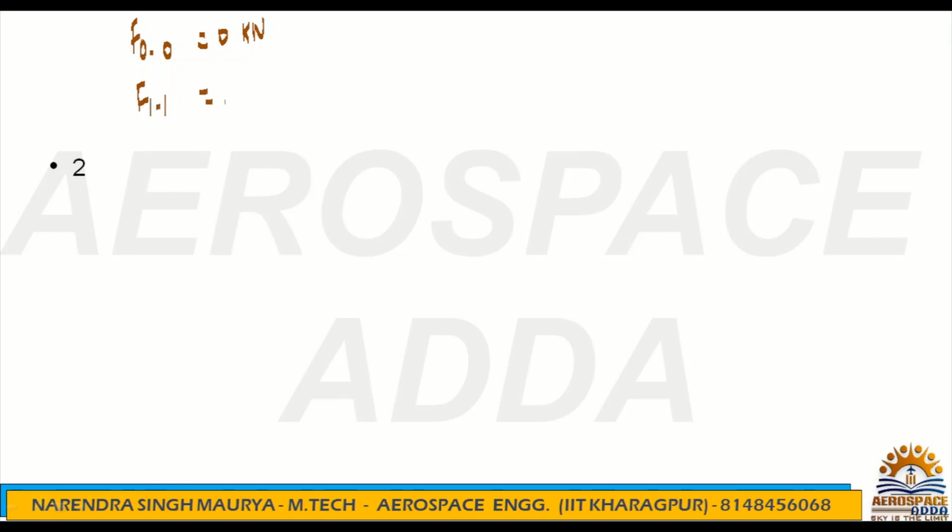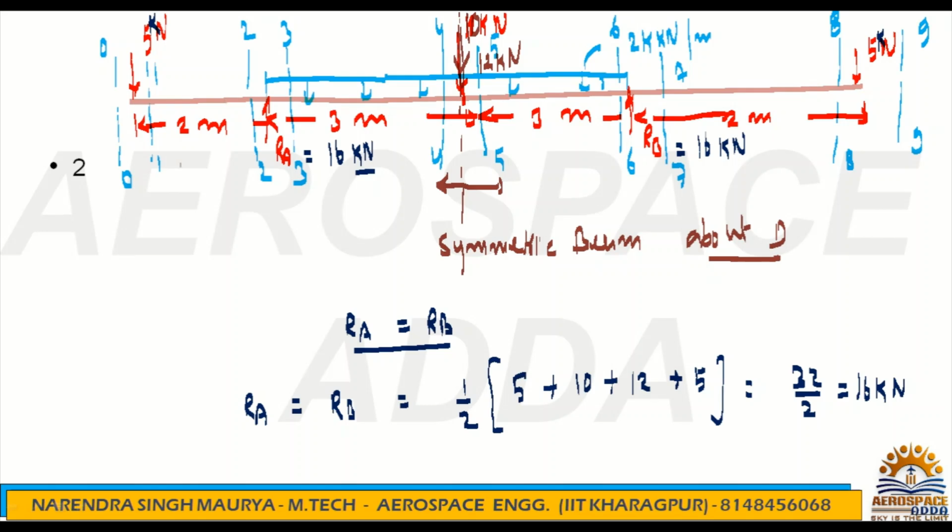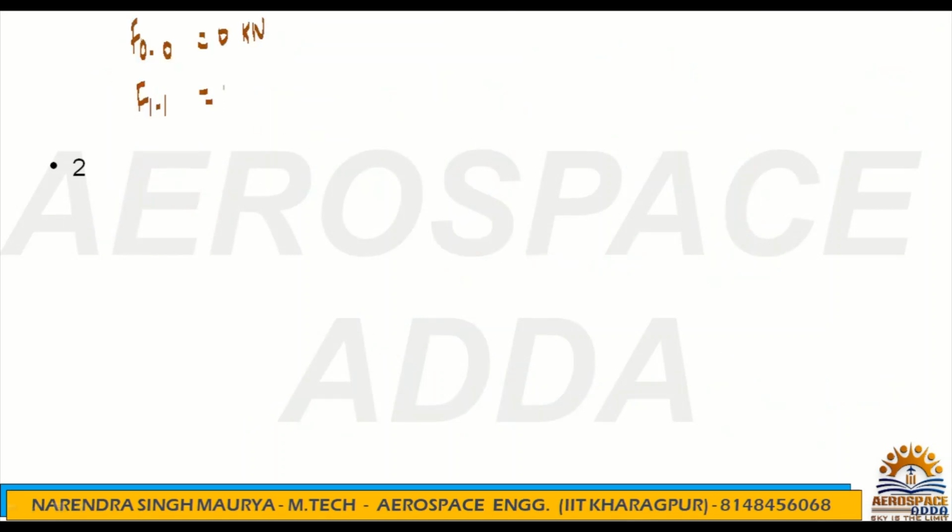It is just after the force, after the 5 kilonewton. For 1 1, you can say left or right. This is the right of the force, and this is the left of the force. In a few books you may get left of the 5 kilonewton. So the left side of the 5 kilonewton, 0 0, the value will be 0, because the force starts after the 0 0 line. And if you check 1 1, before the 1 1 line, one force is there which is 5 kilonewton, and it is acting downwards. So this value will be negative because it is acting downward, 5 kilonewton.